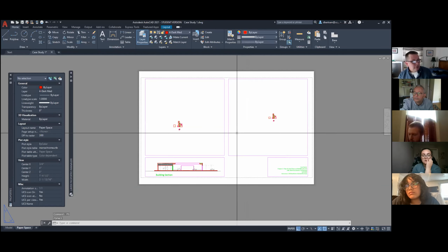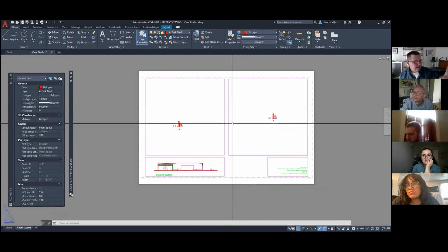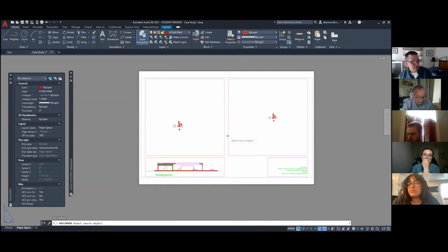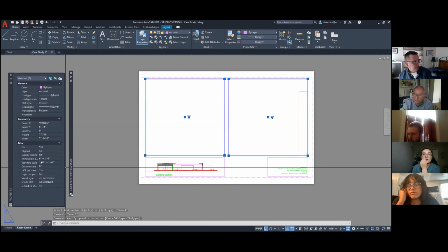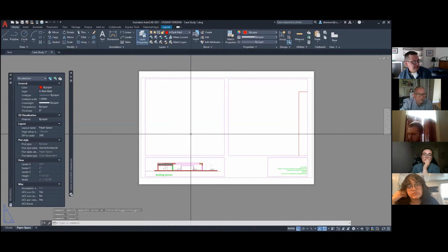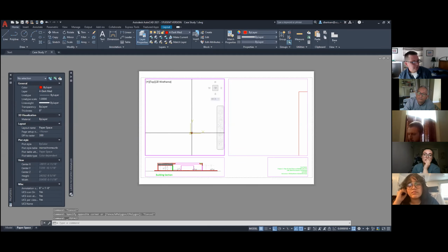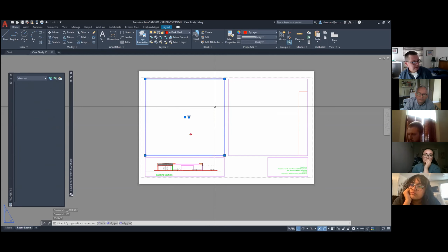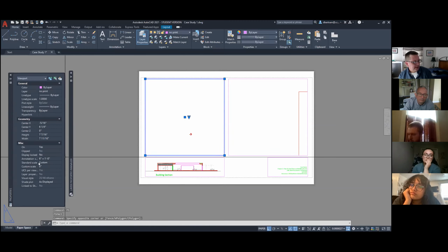So what I have to do is reconfigure the drawing. One thing I could easily do is MA for match properties. Being that I know these three viewports are all the same scale, I could select that guy. And now these two, I've selected them. So they are the proper standard scale at 16. Let me mess them up one more time. So now I jump through, zoomed, PS for paper space, select it, and right there, standard scale, it says custom. That means there's no scale, right?